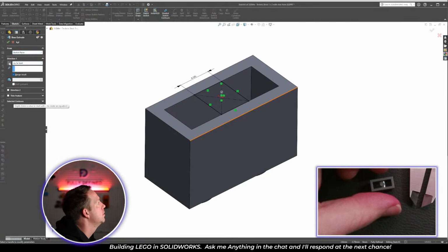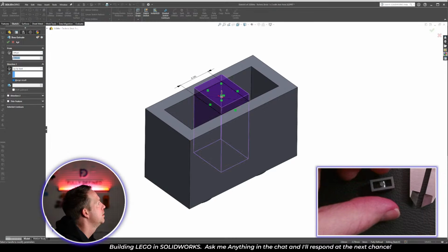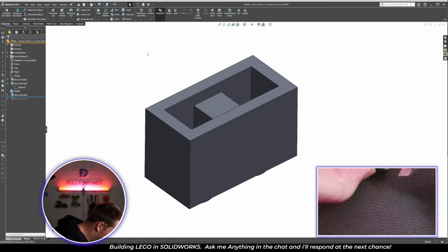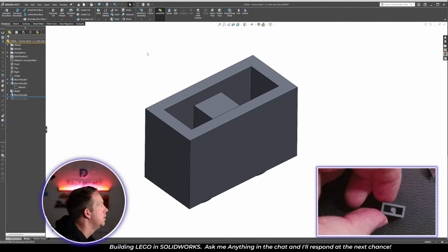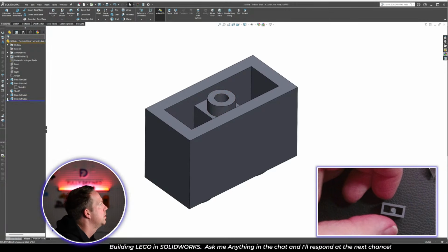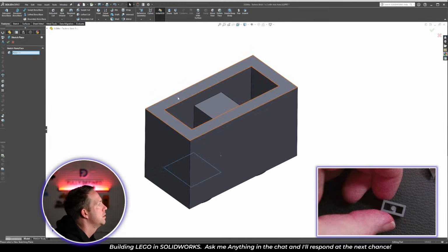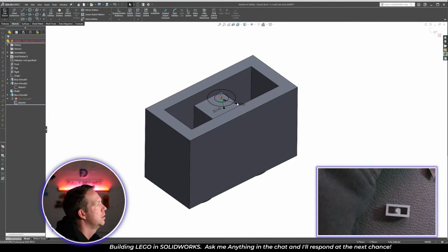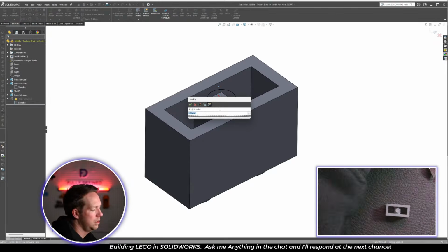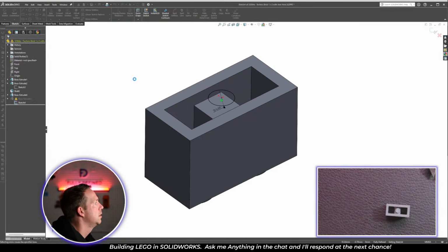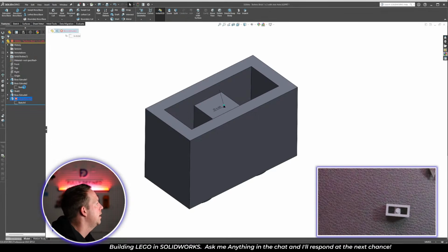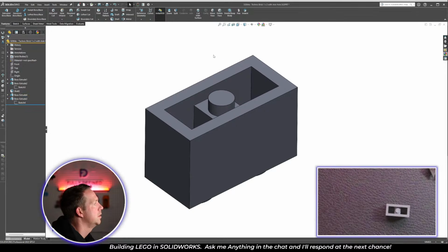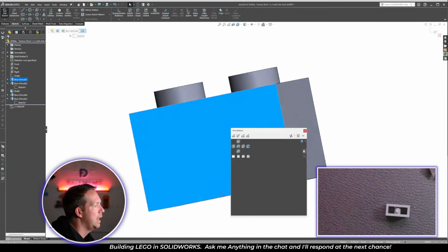We're going to go up to next. We're going to offset it 1 millimeter or a bit more. And then it's got a round bit in the middle that is 3 millimeters. That one there. Let's start on that face. Change the sketch. Get rid of that inside. Change that to 3. And edit this feature to come down to surface.